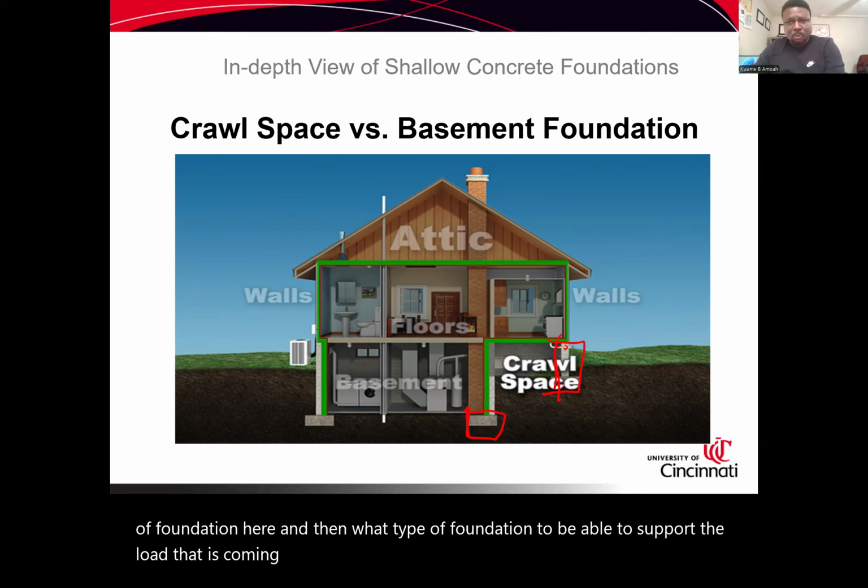All right, so it's a basement foundation. Sometimes all concrete before you get to the slab on grade for your first floor if it is 2 story or more, and then if it's a residential home 1 story, you just have to do your slab on grade here and then make sure your crawl area has adequate support to carry this load.